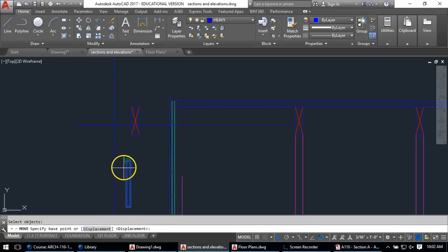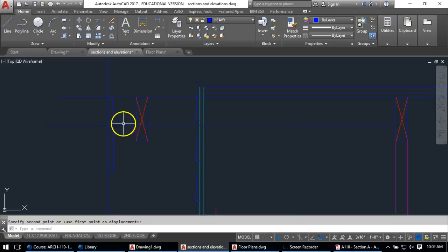And this is going to sit up underneath the sheathing, so I can move this up to there, and that's going to be where my 2x10 is located. And then my 2x6 is going to be next to that, there.